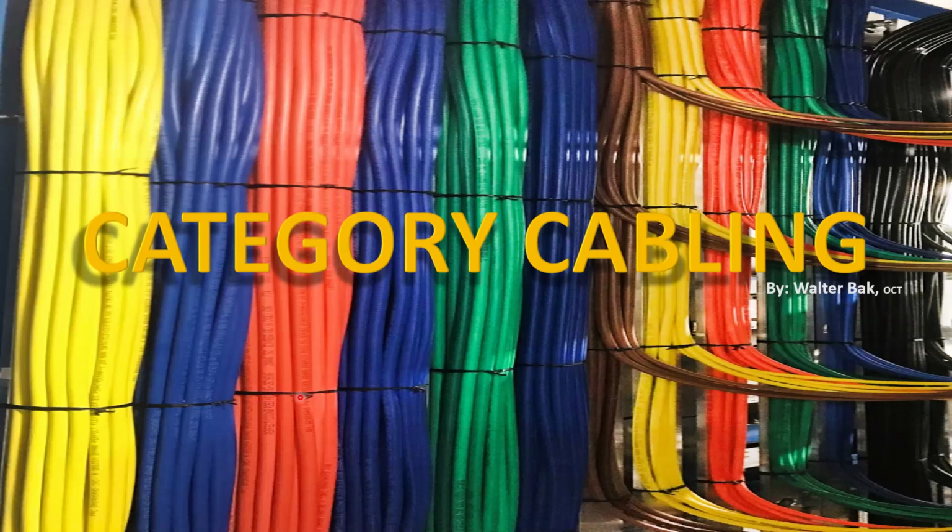So squeezing the cable, deforming the cable, bending the cable too hard or too much, and for sure stepping on it. Or sometimes it pulls out of the box, and we had that yesterday in our lab. The cable was pulled out of the box, and whoa, there was a bit of a knot, and that created a kink. Kinks are not really good news when it comes to Ethernet cabling.